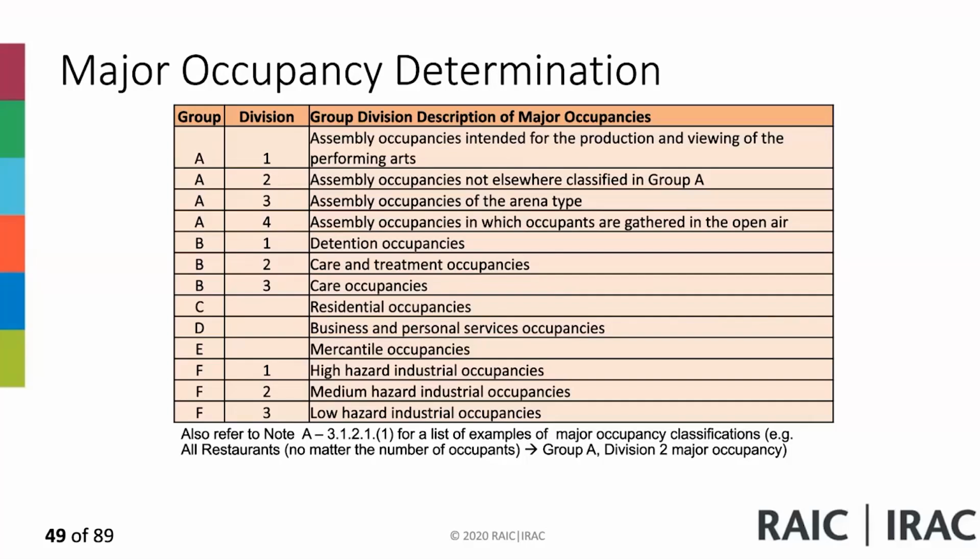So when you have a medical office, it's not necessarily a care and treatment. It's a clinic. In a clinic, you just go see your doctor. He gives you prescriptions, he checks you up. And sometimes your dentist is a medical office. Now, if they start to do clinics where they do day surgeries, then it is your treatment occupancies. So you gotta be careful about your clinics and what they are doing in them.